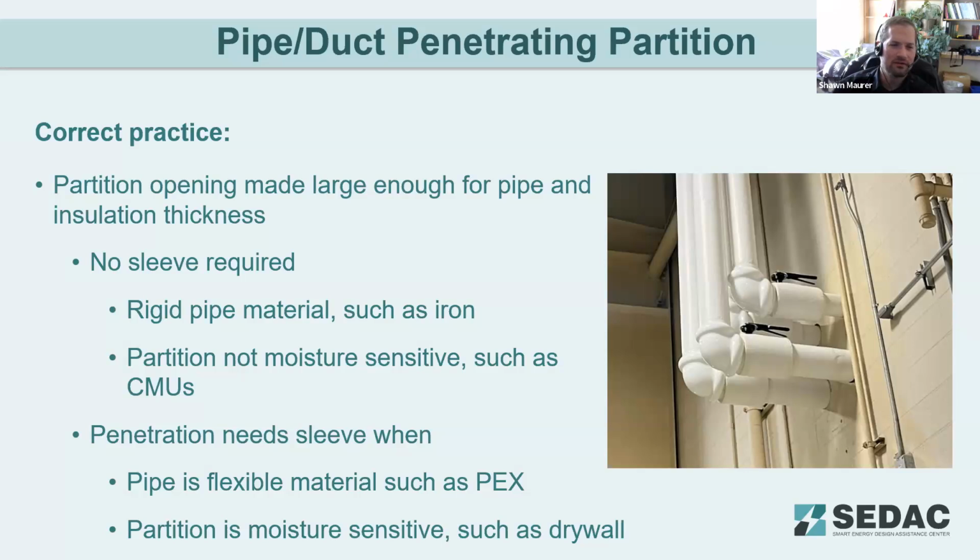We did have a comment on where pipe goes through the exterior wall. The air barrier must be continuous to the pipe, not the insulation. When looking at the pipe insulation, you do need to have continuity of that air barrier. So the pipe jacketing should go all the way through that sleeve penetration and be continuous for the pipe.